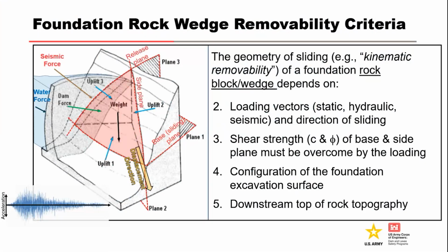We also need to configure and constrain the geometry of the loading vectors and the sliding direction. The shear strength of the discontinuity surfaces providing resistance to sliding must be overcome by a combination of the dam, water pressure and seismic loading.